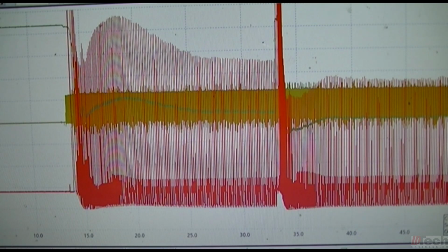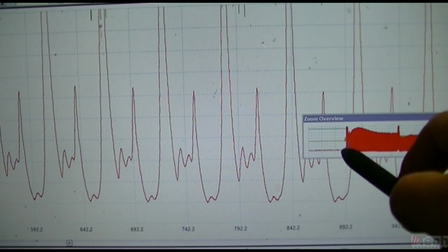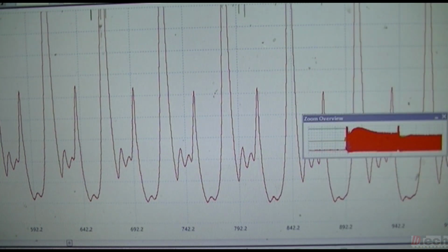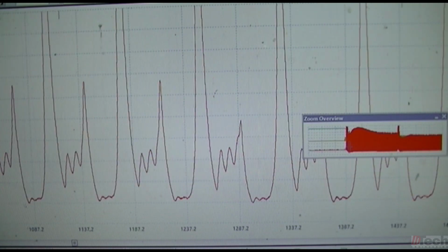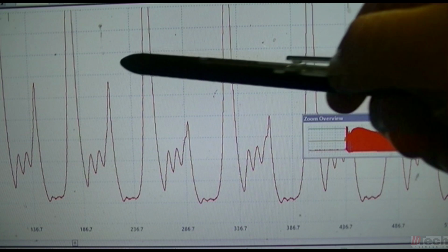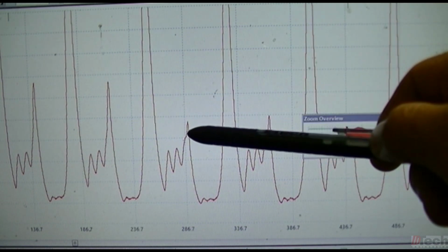Now this is going to be bank 1, the side that we seem to be having issues with. So we are at the very beginning initial point. Obviously it looks about the same, though we know we have a higher pressure range in that area on this bank. We'll scroll through, and there we see phasing occurring. We see it drop down,